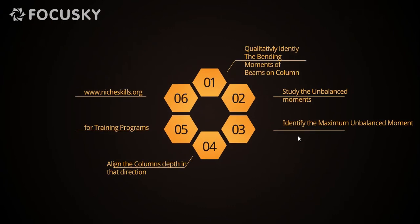When you are working on column orientations, qualitatively identify the bending moments of beams and columns, study the unbalanced moments, identify the maximum unbalanced moment and the beam from which it is coming, and align the column's depth in that beam's direction.